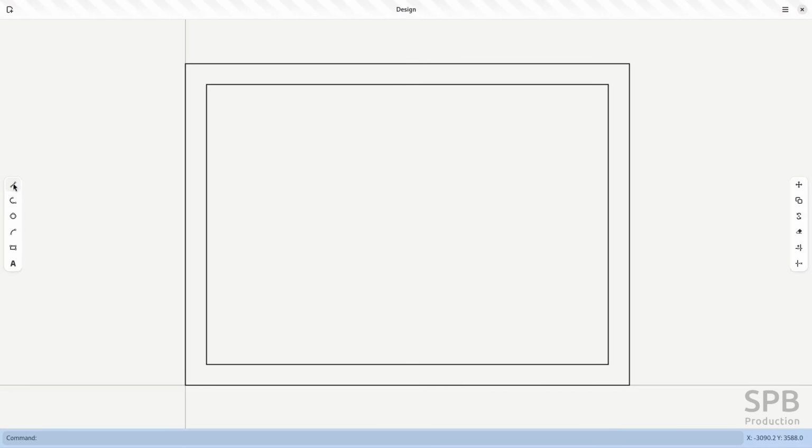So what I can use is I will start the line tool, and if I click here, by default, I have got polar tracking turned on, so if I move my mouse in this direction, it snaps to the orthogonal angle. Now I can use that I'm pointing the direction with my mouse, and if I type in 400 and hit enter, it created this line 400 millimeters long in the direction that I was pointing with my mouse. So you can also know this technique from AutoCAD.